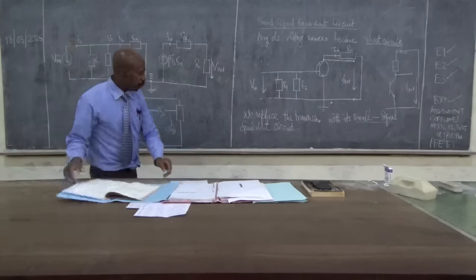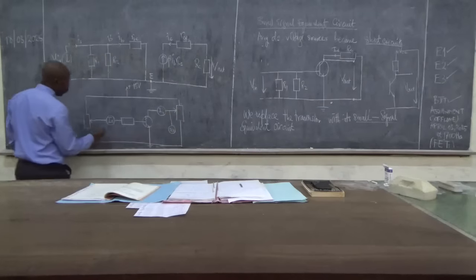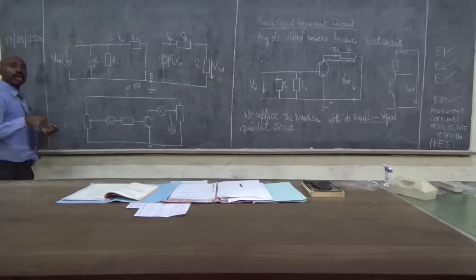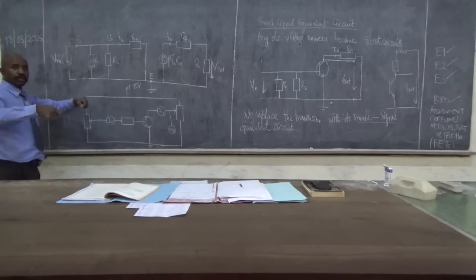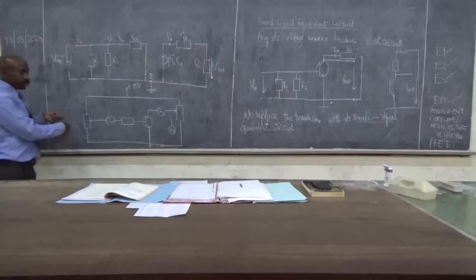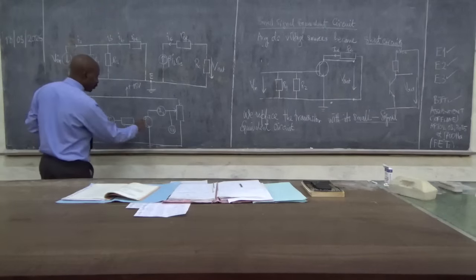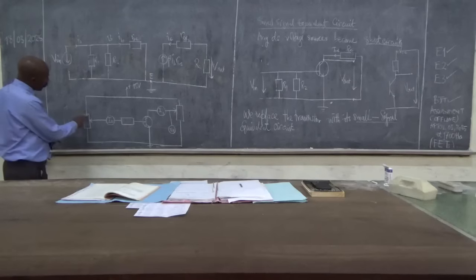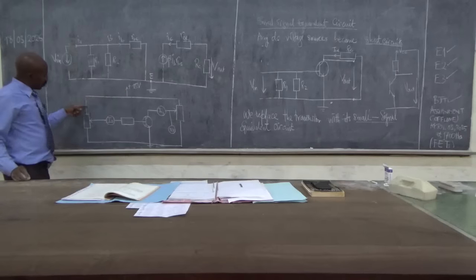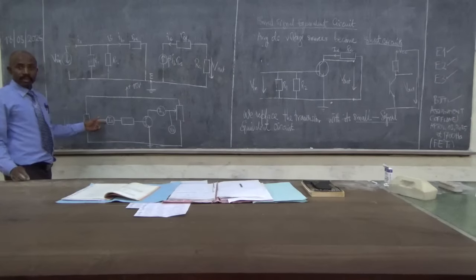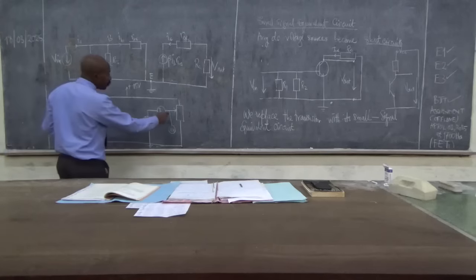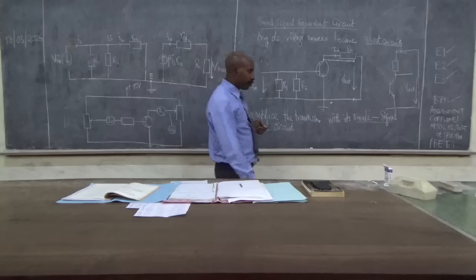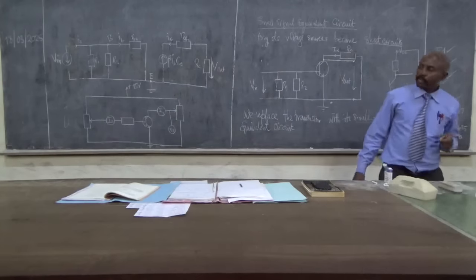So you have two potentiometers. When you are in here, you are trying to vary the current that goes through here, IB. So you can vary IB as you read off IC and VCE in order to get the output characteristics.